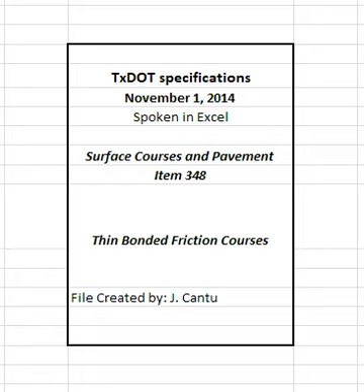When the estimated magnesium sulfate soundness loss is greater than the maximum magnesium sulfate soundness loss specified, the coarse aggregate source will not be allowed for use unless otherwise approved. The engineer will consult the Geotechnical, Soils, and Aggregates Branch of the Construction Division, and additional testing may be required before granting approval.